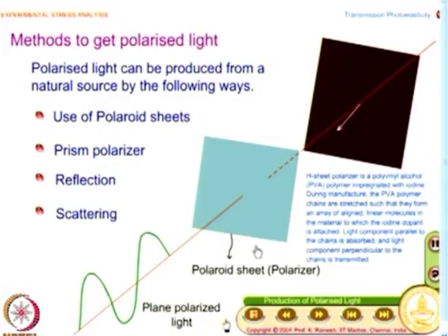And if you look at polarization, birefringence, and also formation of the light ellipse, they are interrelated concepts. You have to go back and forth to understand, and then get on to solid mechanics aspects, and then look at how to relate the optical phenomena to stress information. And first look at what is polarization.